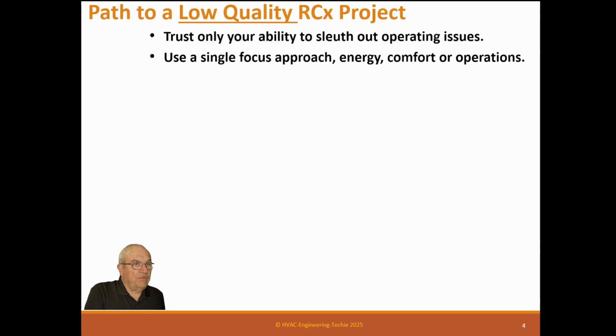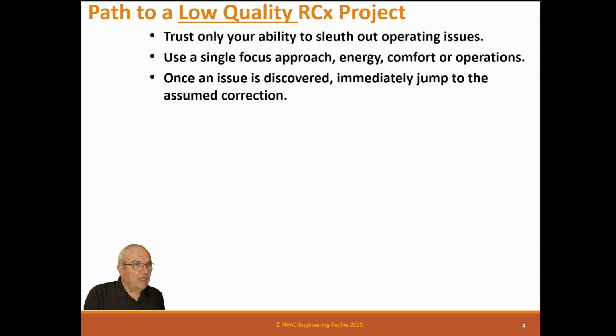Using a single focus approach, such as energy, comfort, or operations. You need to be holistic in nature. You need to look at everything. Once an issue is discovered, immediately jump to the assumed correction. This is a pit you can fall into if you're not careful. Oh, yeah, I see that. Well, I know exactly how to correct that. Don't do that. Just write it down as an issue and look at it later, because most of the time there's more than one problem affecting an issue. You need to be careful with that, because if you don't, you'll end up treating symptoms.